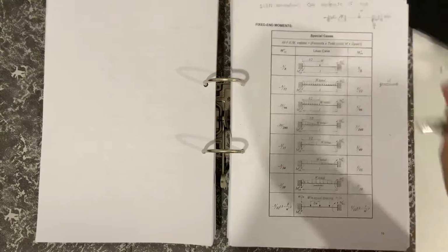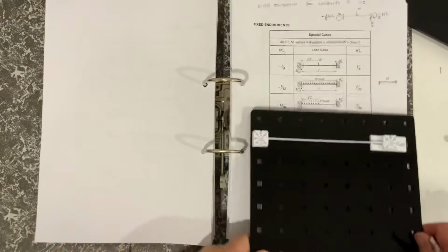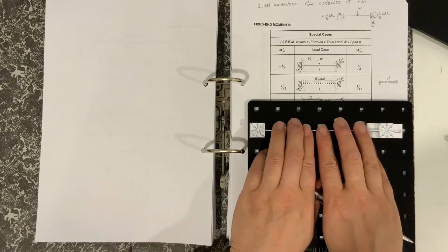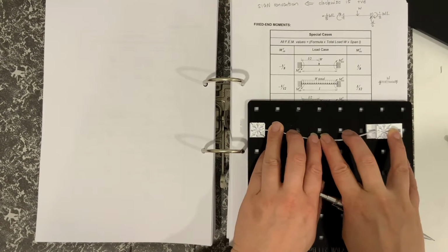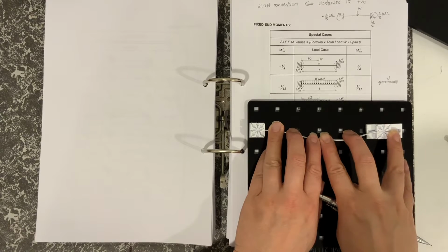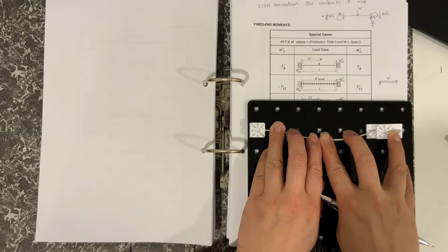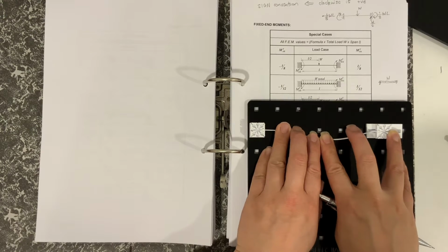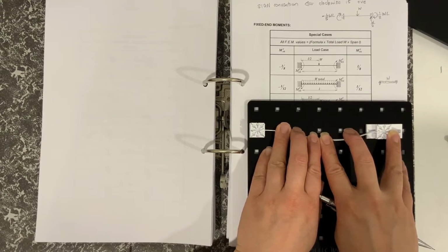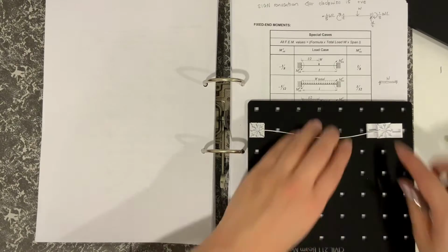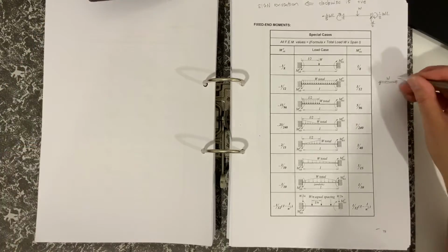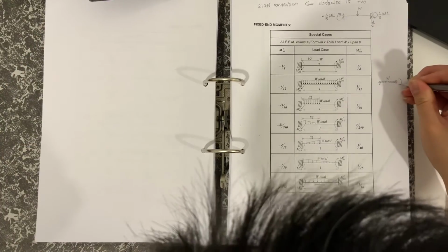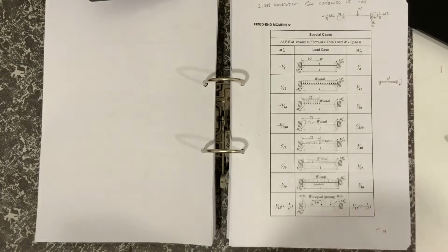Again we've got the beam and both ends are fixed in, so we're going to be calculating the fixed end moments. Both ends are fixed in, so my fingers are going to try to approximate a UDL, so you can see the deformed shape here. And we can again see that the reaction moment at the right hand side is going to be in the clockwise direction, which we'll show like there.